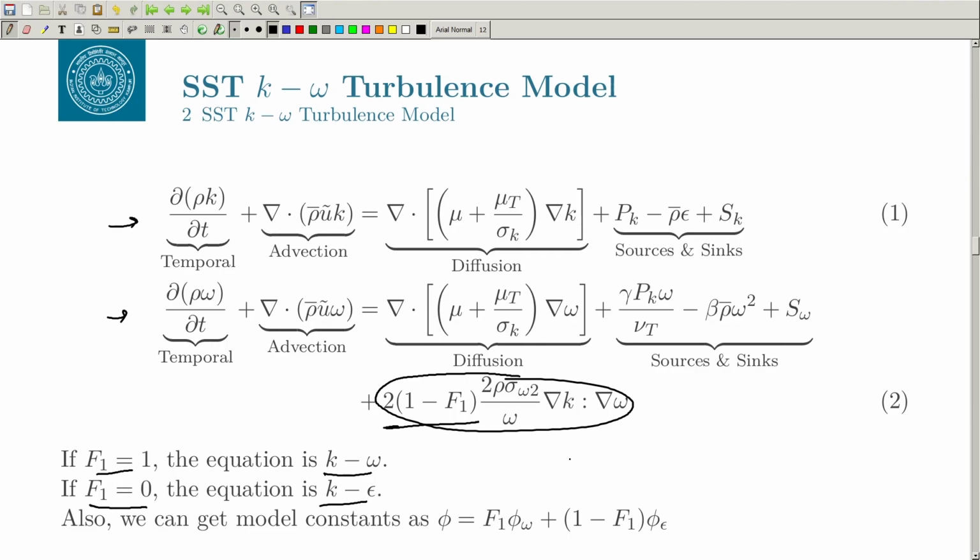One thing I am not explaining: I have been using this term gamma. For now you can take gamma equal to 1 for all this flow. Gamma is a representation of intermittency, which I will talk about very soon, maybe today or in the next class. It is like if you have a boundary layer which is basically laminar and that becomes transitional and then becomes completely turbulent.